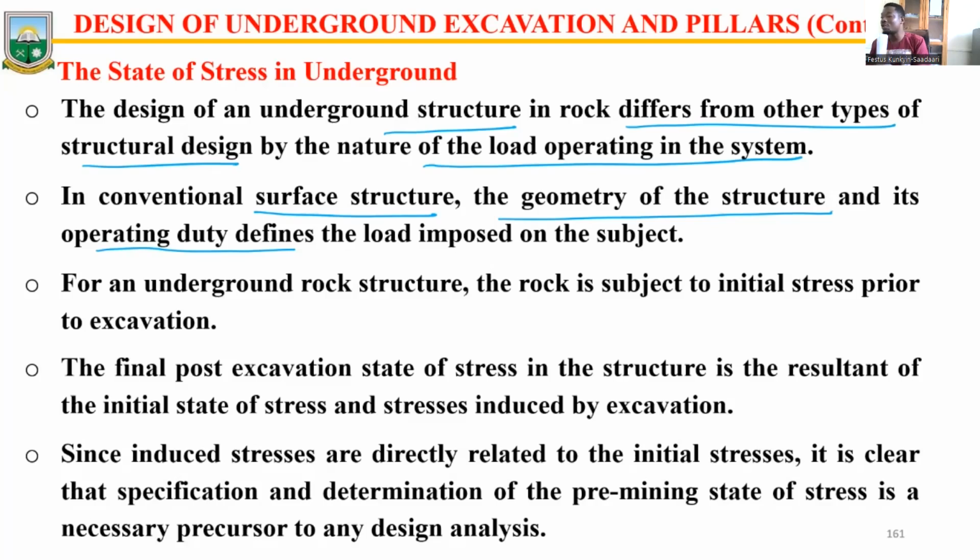For an underground rock structure, the rock is subject to initial stresses. So the formation is already there. It is carrying stresses already. Unlike normal conventional materials, like you coming to put up a building and your roof, you have no stresses up there.